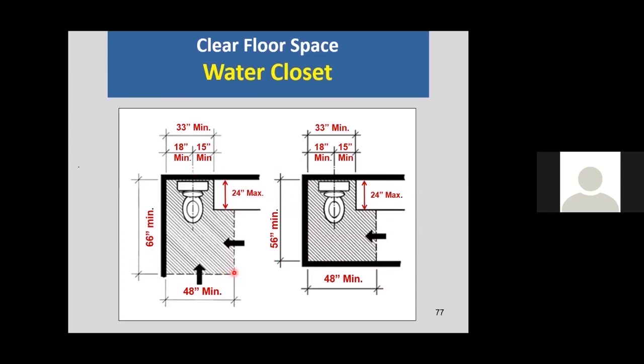Where you put the toilet in the clearance has changed a little. HUD's design manual requires 18 inches absolute from the side wall, and then 15 inches at least to any other overlap into this clearance. That other overlap can only project 24 inches into the toilet clearance. If we're not next to a sidewall, maybe it's a bathtub, we have an 18-inch minimum requirement.